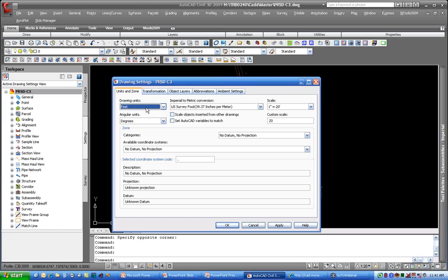And what it was is we had the wrong units set up here. We were working in inches, which didn't quite make sense. So definitely want to come in, make sure your units are feet. If you're importing and exporting anything to meters from a project using feet, you do need to specify what unit you're using here, so I'll set that. And then I also have my default scale, and I'm working at 20 scale today just because it makes everything easier to see on the screen.